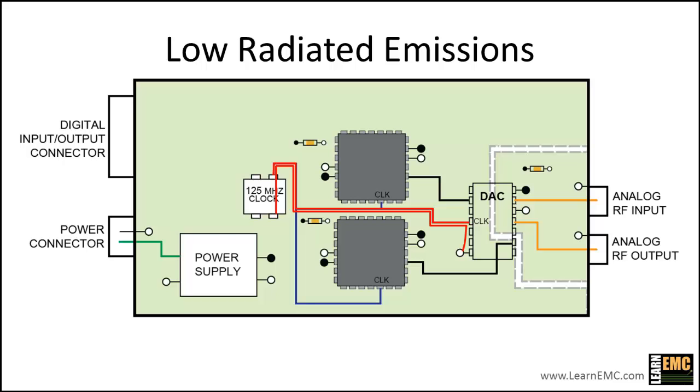On this board, our analog signal is also RF, so the analog return currents are going to behave in the same way. Those currents will come out on the ground pin nearest the trace, and they're going to flow right back to the connector underneath the trace.